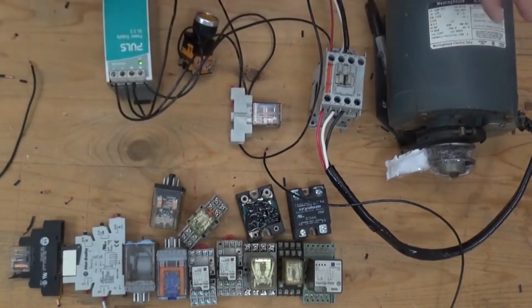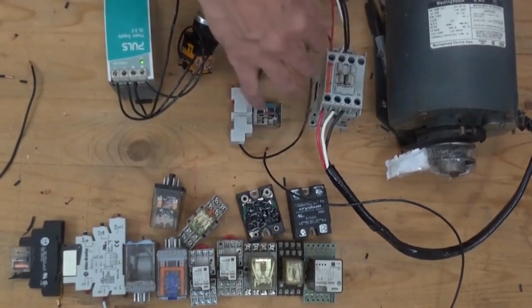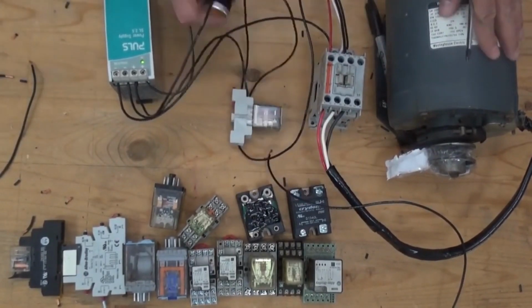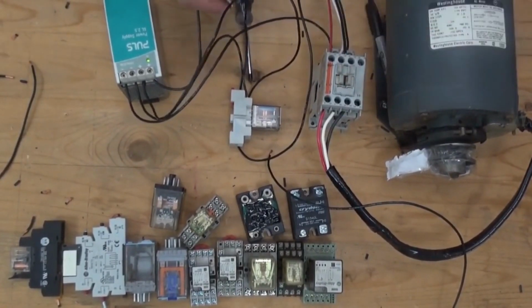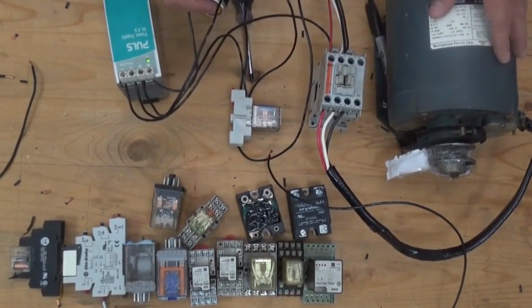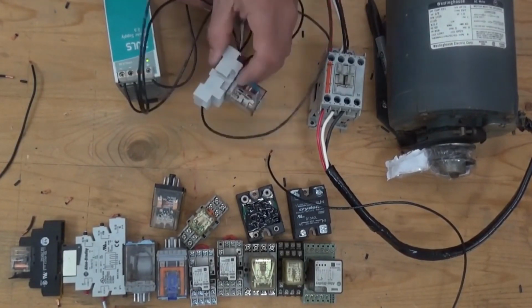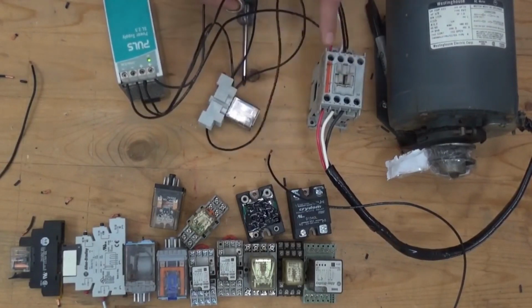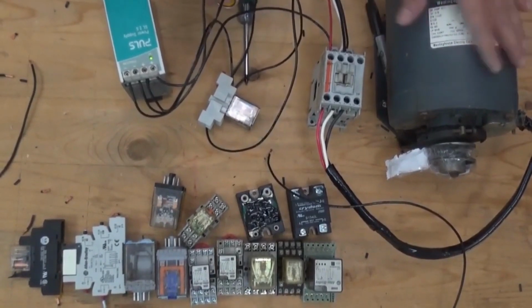In this scenario guys, I didn't plug in yet the motor, but anyway, I already connected the power circuit of the motor. When I press this, it should plug in. It doesn't run yet because I didn't plug in yet the power supply. Let's try. Okay, both of them are plugged in. The relay energized and the contactor energized. Once I plug in the power source, the motor should run.